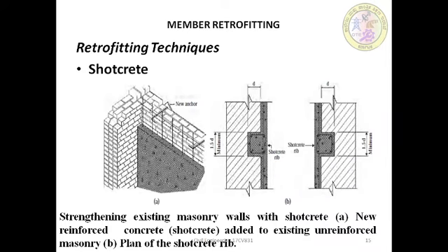There are two types of shotcrete usually employed, namely wet mix, for large volumes and massive sections, and dry mix, which is called gunite, for lesser volumes, thin sections and confined spaces. Better control can be achieved in handling the dry mix shotcrete as compared to the wet mix due to good control of the material flow.